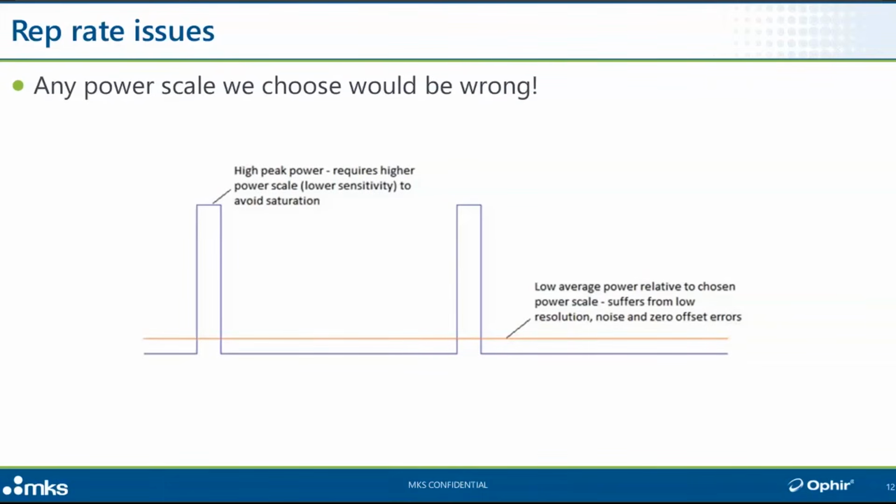And even worse, because the average power is within the range of the scale, my instrument might not even realize that we're over range, and so the user won't be given any kind of a warning that something's the matter. But because during the course of the pulse the sensor and the meter were momentarily saturated, the reading could very possibly be wrong.